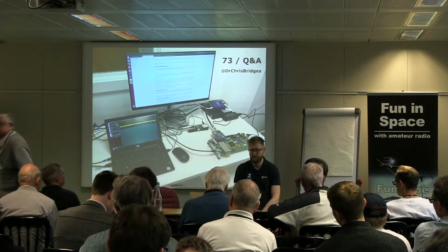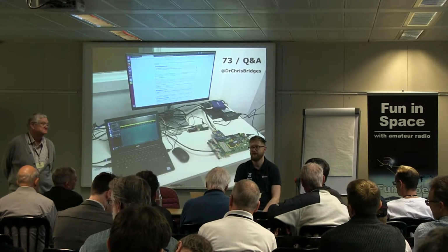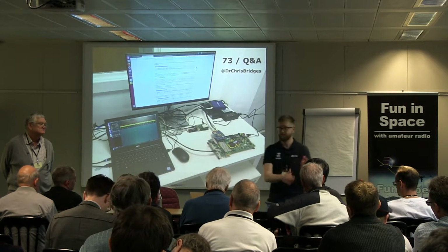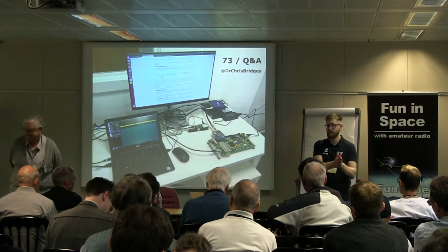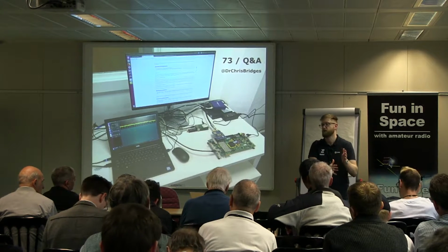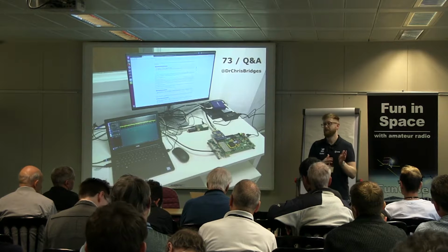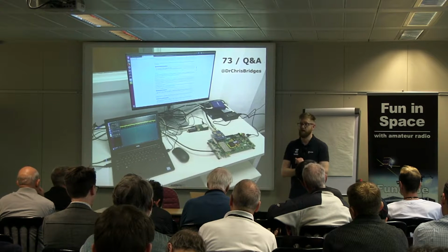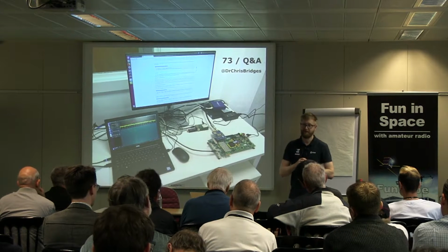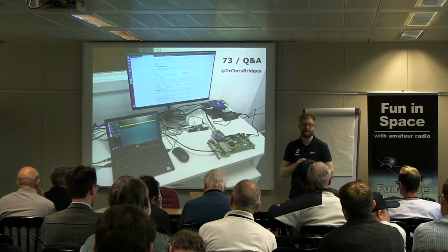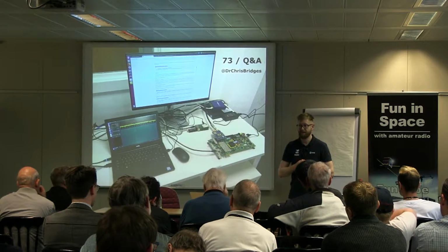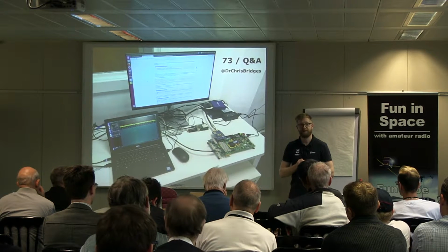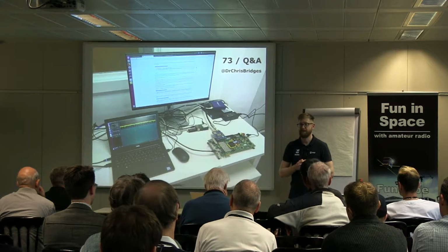Now, I'm doing something quite unique on this because for the work that I've done on Raspberry Pis, I actually have research that doesn't just look at the silicon to understand really where the damage goes, how you mitigate it, and functionally what do you do to change it in software. But also I have a PhD student who's been building a compiler for doing TMR of the caches and the processor registers. Okay, so there are some unique things added to that mix. I would add as well that the amount of ionizing dose that I have given these things is an order of magnitude bigger than what you would expect to see.